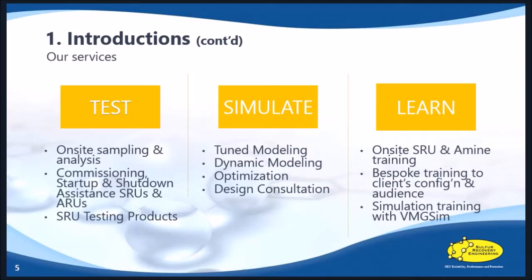And there is one more very interesting thing over here, which is the tuned dynamic model, or tuned modeling. A tuned model is a steady state model at the beginning. However, it matches the performance of your unit on its stages of converters, reheaters, and reaction furnace. And by using that model, you can do offline studies regarding troubleshooting or any cause and effect analysis.